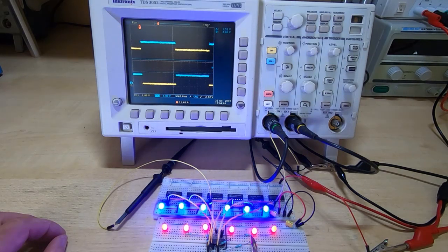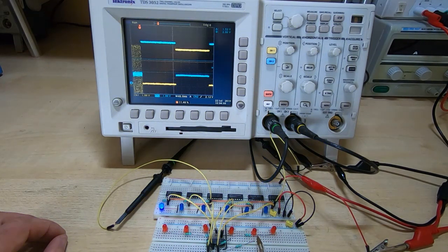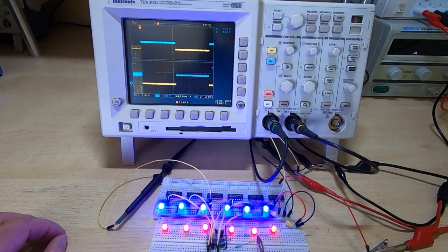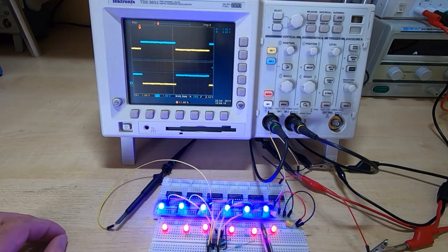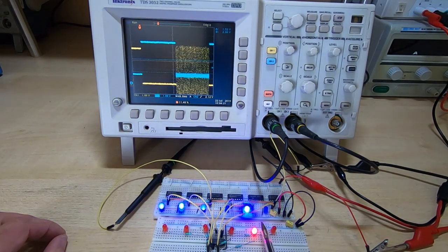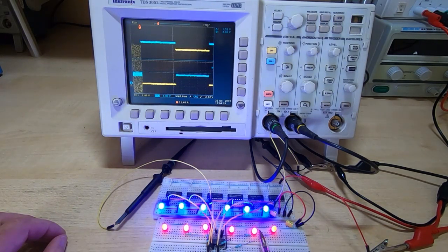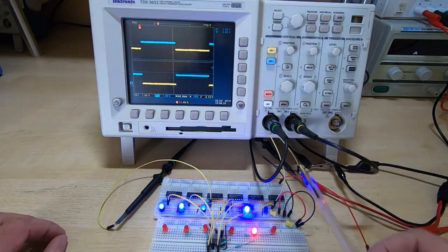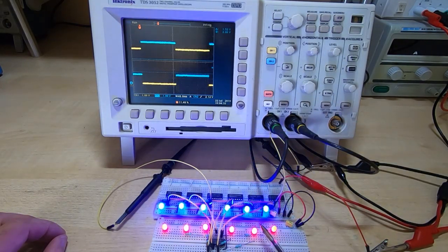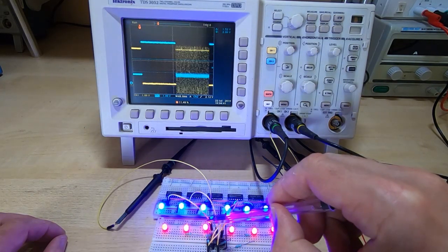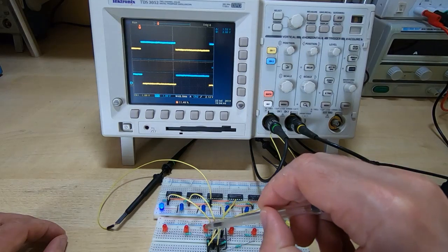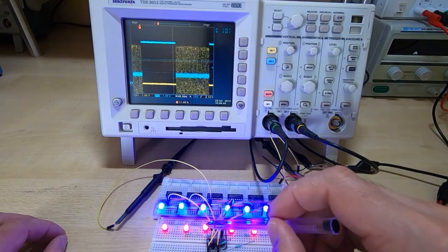of thing. What's odd is you can see that the device adjacent to it doesn't like this noise that it's seeing. It's a Schmitt trigger, so this is quite sensitive to switching, and it will switch one way, and then it needs obviously the hysteresis to be overcome before it will switch back the other way. So it does tend to smooth out this type of noise, but that can in itself cause problems. But this particular device that we're monitoring appears to be still switching exactly as you'd expect it to. So this blue LED and this red one, even when it's showing instability, it still appears to be switching.